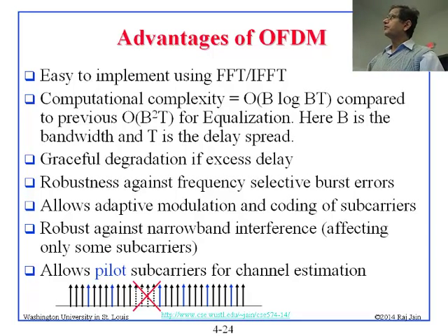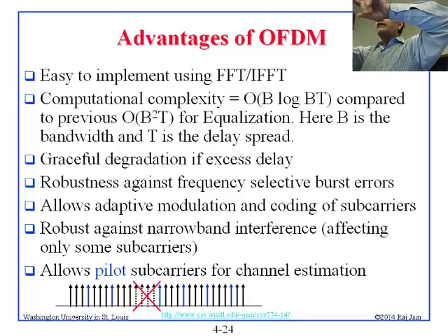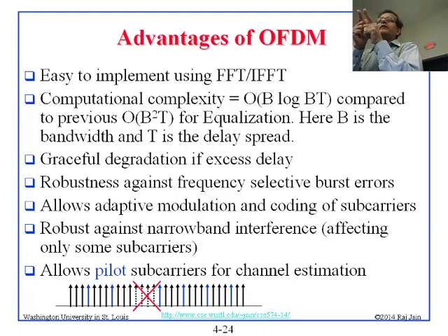But there, you have to do equalization because the amplifiers do not have constant amplification. But we still have to equalize the signal, right? Before the computational thing. Oh yeah, right. So hold on. If you have a 10 kilohertz channel, you can find a good amplifier that will keep it constant for 10 kilohertz. But if you have a 10 megahertz channel, it's very expensive to find an amplifier that will keep constant amplification.